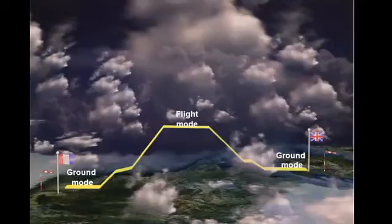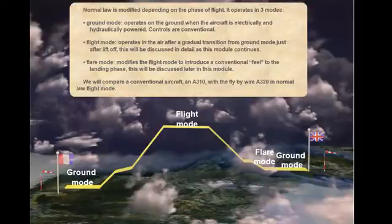Flight mode operates in the air after a gradual transition from ground mode just after liftoff. This will be discussed in detail as this module continues. Flare mode modifies the flight mode to introduce a conventional feel to the landing phase. This will be discussed later in this module. We will compare a conventional aircraft, an A310, with the fly-by-wire A320 in normal law flight mode.